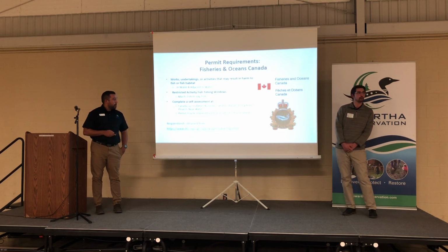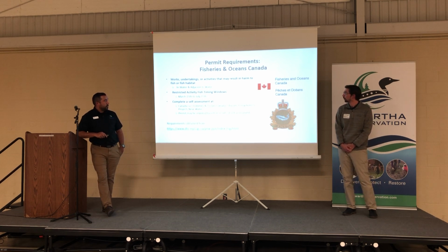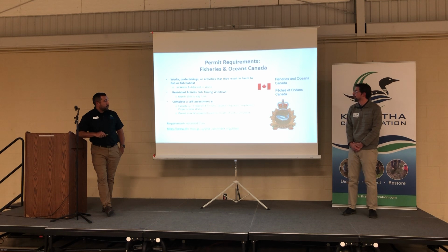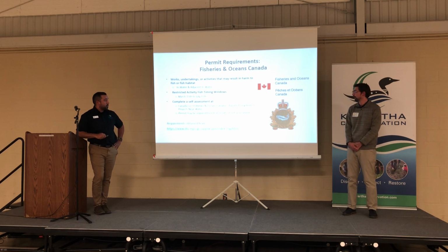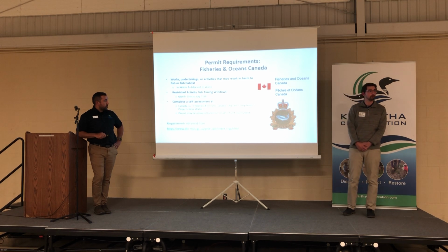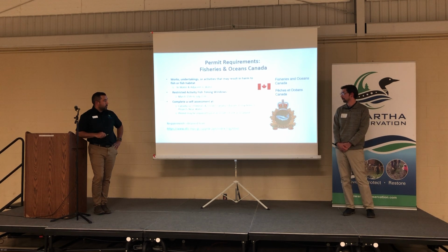And lastly, there's the Department of Fisheries and Oceans Canada that may be interested in giving you permission or approving your works. For works, undertakings, or activities that may result in harm to fish or fish habitat, which includes work in water or adjacent to water, you'd want to reach out to the Department of Fisheries and Oceans, and they may have provisions related to sediment and erosion control that they would apply to your proposal. There are restrictions for activity due to fish timing windows. Generally, March 15th to July 15th is when that would occur. And you can complete a self-assessment to determine if approval will be required from the Department of Fisheries and Oceans Canada by visiting the Government of Canada website, Fisheries and Oceans Canada, Aquatic Ecosystems and Projects in Water.